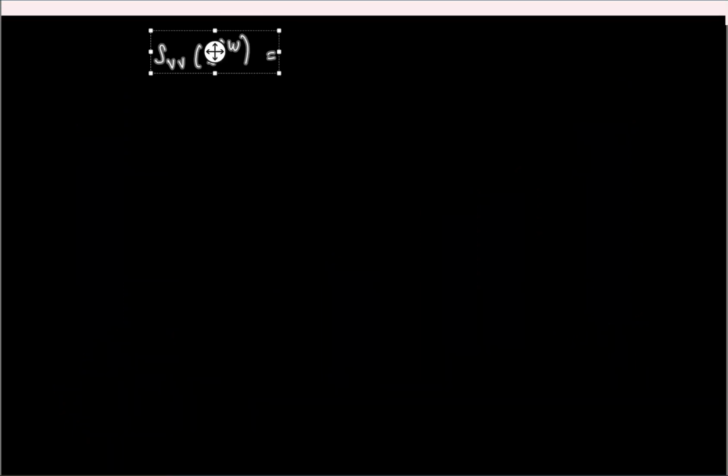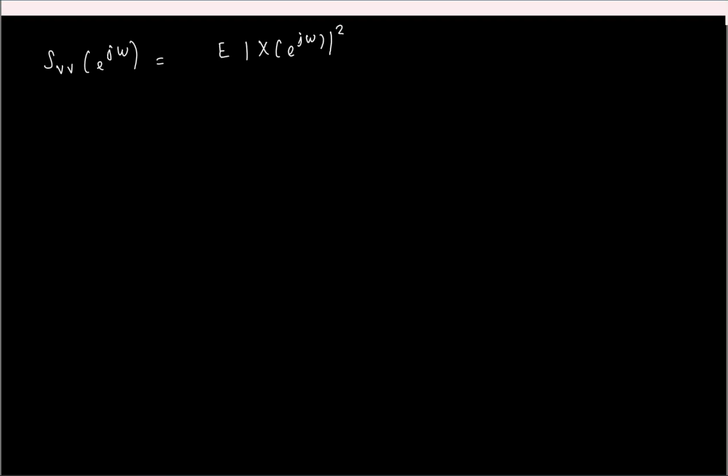So we started off with this, right? We were trying to find the power spectral density of our ADC output, and we initially computed it as magnitude squared of the discrete time Fourier transform, expected value of it scaled by n. Okay. And now we will no longer compute this discrete time Fourier transform. We will take the discrete Fourier transform. So we will compute the power spectral density as expected value of mod x of k square, that's all.